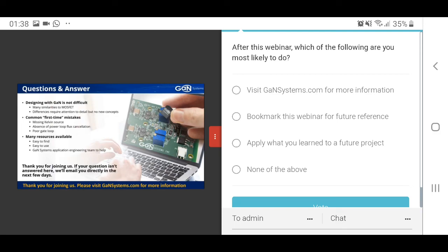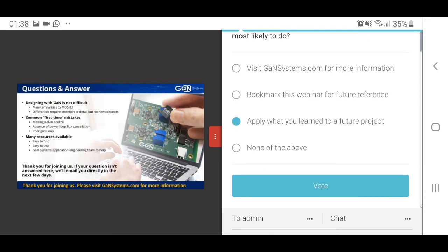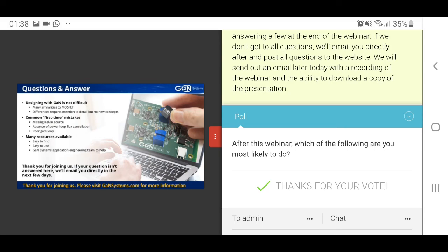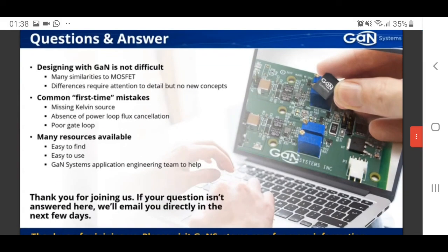The second question is whether the switching loss will be affected by the parasitic inductance. Yes, the answer is yes. A very obvious example is the common source inductance. It will slow down the switching transition. And in some worst cases, there could even be fault triggering. So the switching loss will be very different.